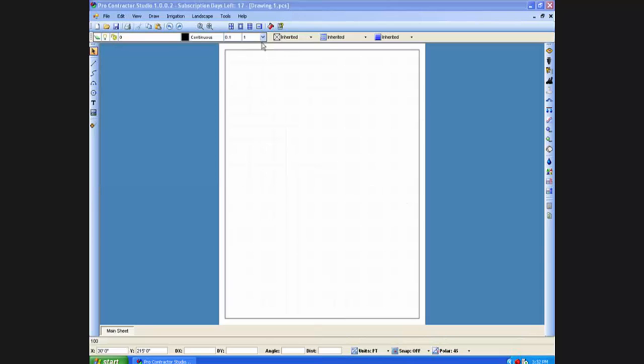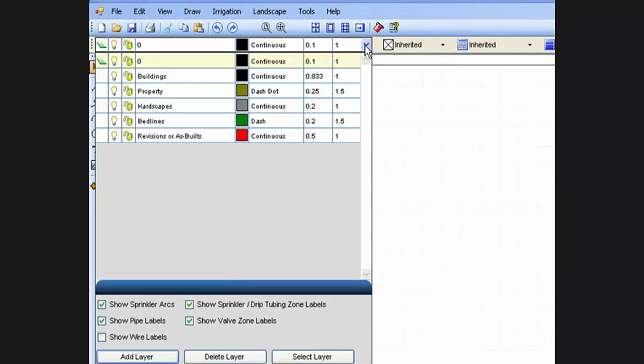First I switch to a building layer and line style. It is important to make sure you are drafting on the correct layer assignment. These layer selections are included in most of the existing templates. If you are starting a new drawing, make use of the Layer Manager to create the drawing layers.